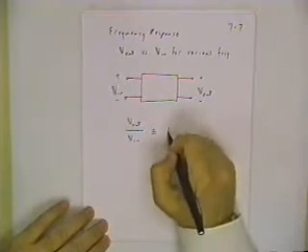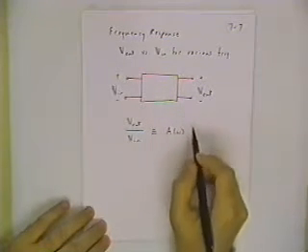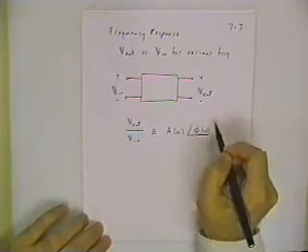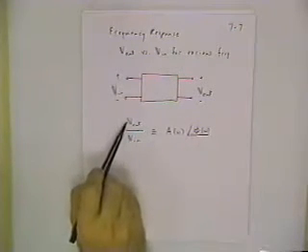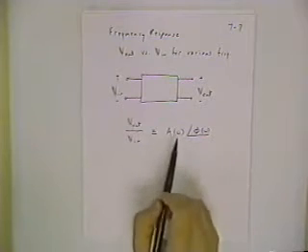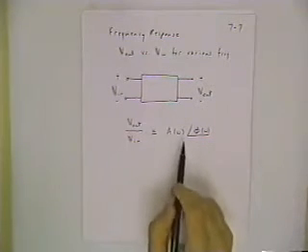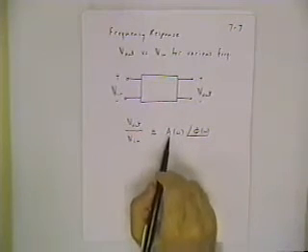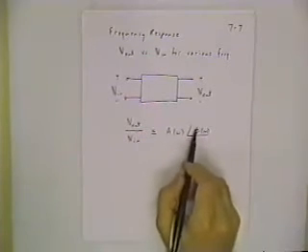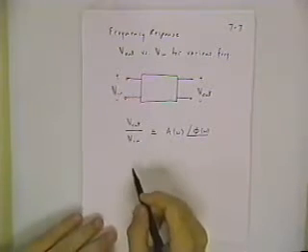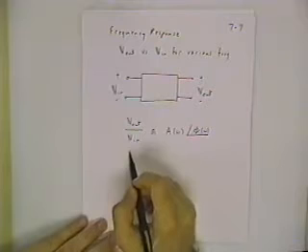And that's defined to be an amplitude function of frequency and a phase angle function of frequency. Now, if you think about it for a second, the voltage phasor has amplitude and phase angle parts. The voltage phasor here has an amplitude and phase angle. So the ratio of those two, logically, would be in this complex form, the polar notation, amplitude at a certain angle. And what we're going to explore now is how do these amplitude and phase expressions take shape for low-pass filters, for high-pass filters, for capacitor, resistor, inductor circuits.